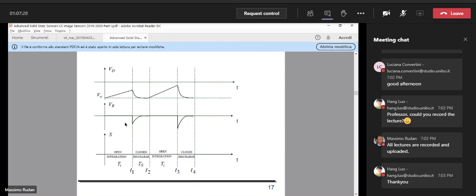Okay, and as we commented yesterday, if you use this type of device to form an array of pixels for a video camera, and the period of the video camera, the period is Ti plus Ts, of course. Okay, so the signal has a period that is the sum of the integration time and the sampling time. Okay, if this period is smaller than the so-called retention period of the brain, okay, presenting static frames gives the illusion to the viewer of an image that is moving. So this is the principle on which, for instance, displays like TV displays or computer displays or whatever are based on.